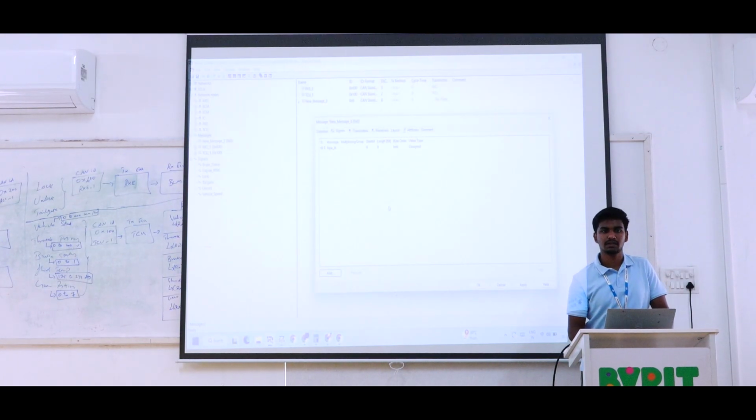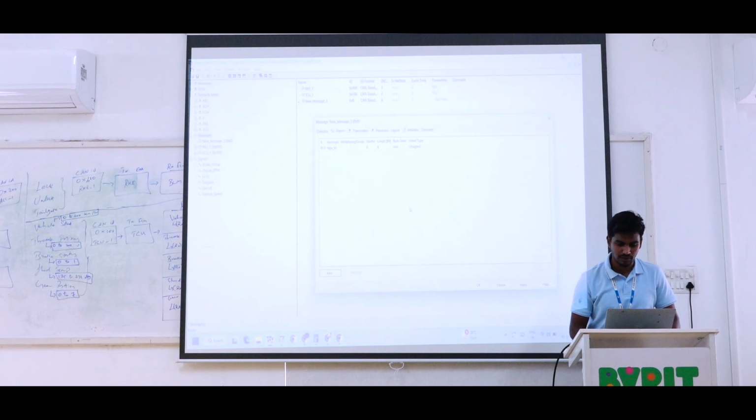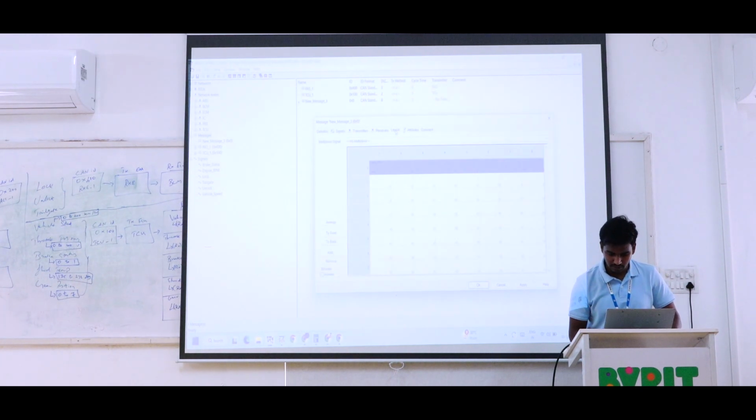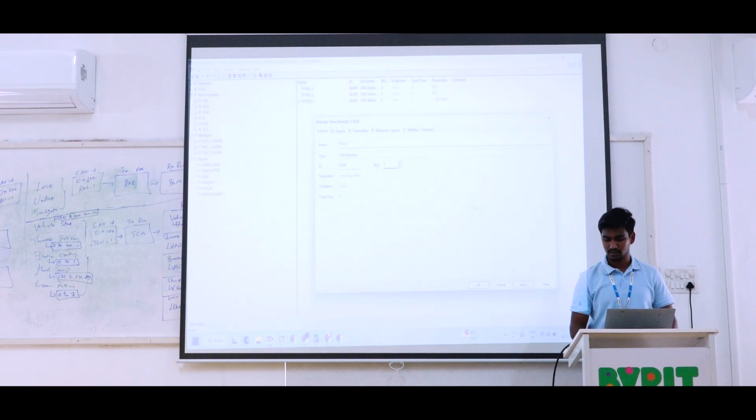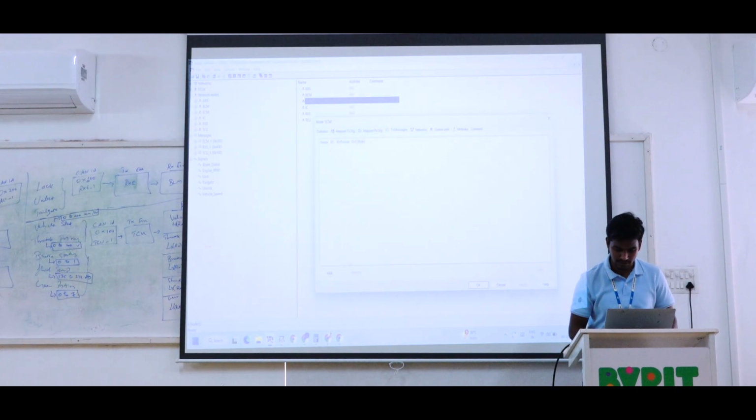So what signals have we created? We need to map at least one of the messages. So for understanding, I am creating just a new message for the engine. In this layout we have given only one DLC because we are carrying only one signal. So now we are creating. We already have the engine control module, so it is going to transmit. So transmit messages, add. The transmission ID is 300.